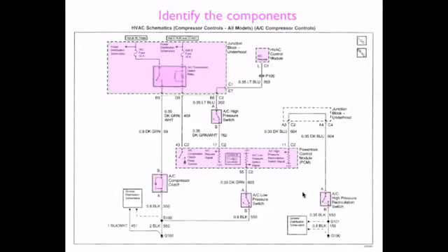We have our AC high pressure recirculation switch. Now this switch is open, so at rest it is open as opposed to these which were closed. So things coming to this switch will stop because it is an open. We're going to talk more about this at the end of the diagram. And then there's another part of that junction block under the hood up here.